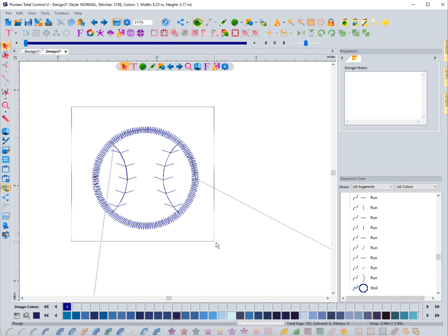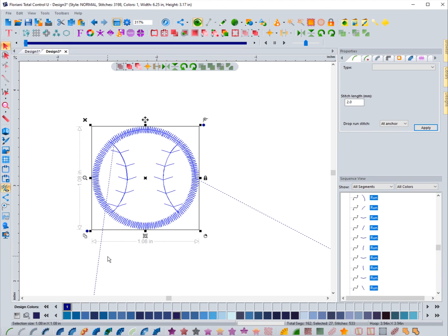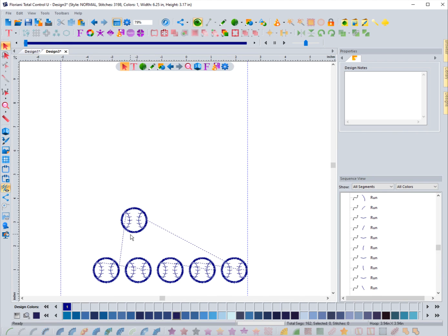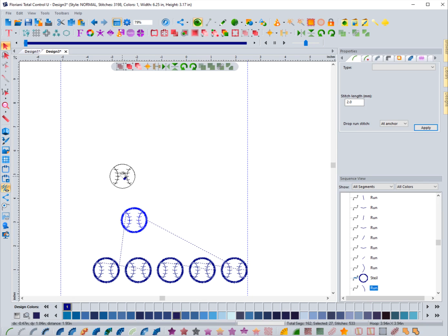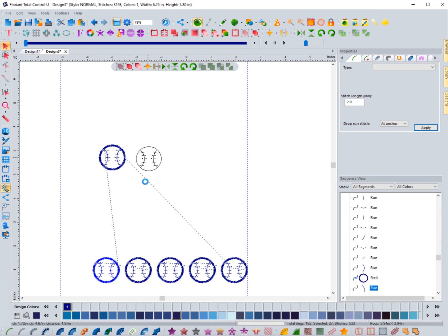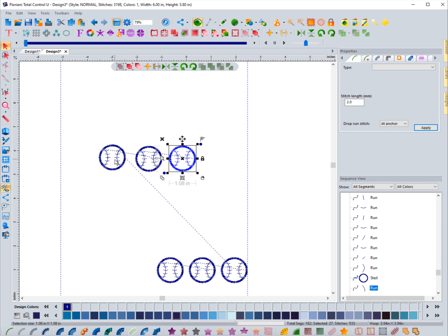It's important to know how to group and ungroup objects, especially when you're looking at transforming something, like with the alignment tools or the distribute tools, because it'll affect how it behaves. And so if you want the entire baseball to work with each one of these and not kind of treat the individual pieces separate, you want to make sure that each are grouped.